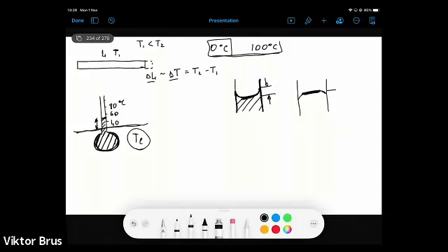And that also depends on the difference between, let's say, air temperature and liquid temperature. So the higher the difference, the higher this pillar of mercury outside the measuring environment, the larger will be this error. So that's just a comment that even measuring temperature with a liquid thermometer requires quite a serious approach in order to get the highest accuracy.